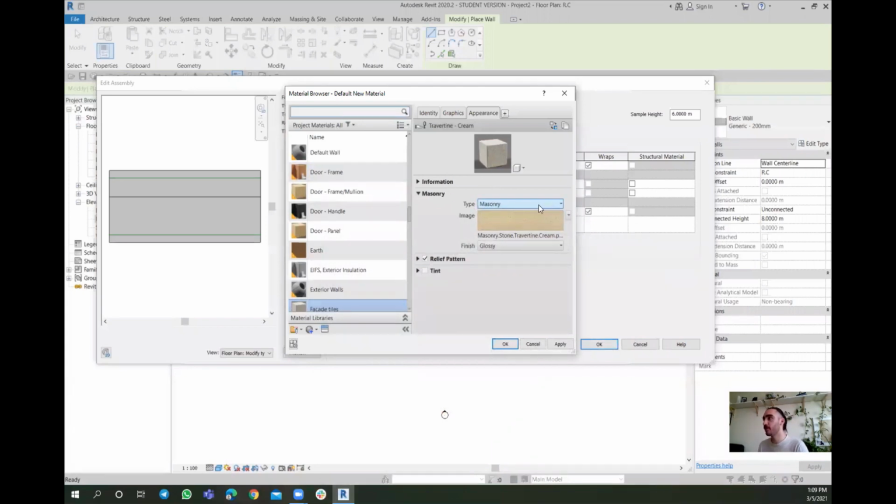The type is masonry, meaning I can choose either CMU or masonry. Sometimes the backup information or the visual weight might be a bit different, so go with whichever you technically need according to your own design specifications, right?